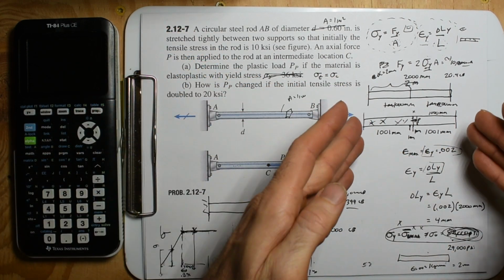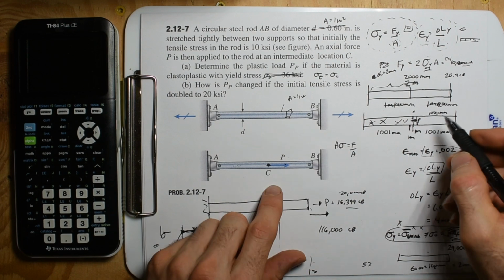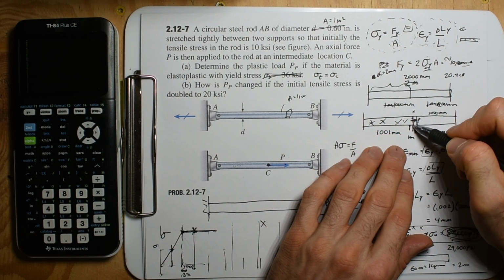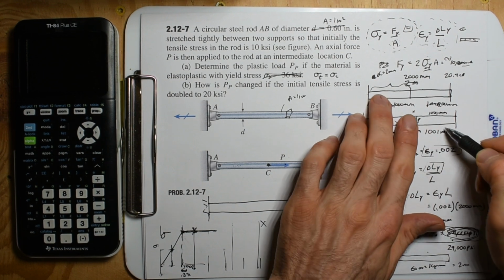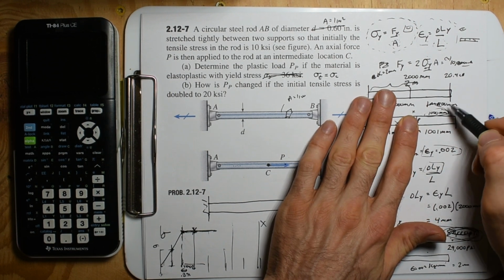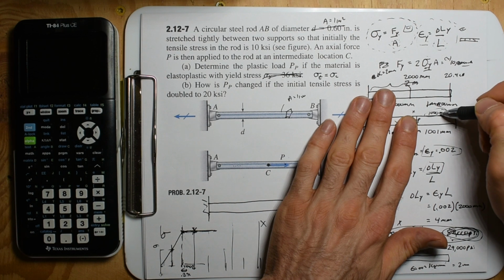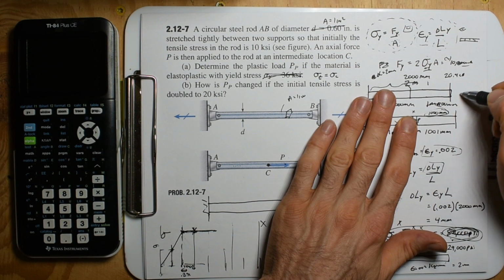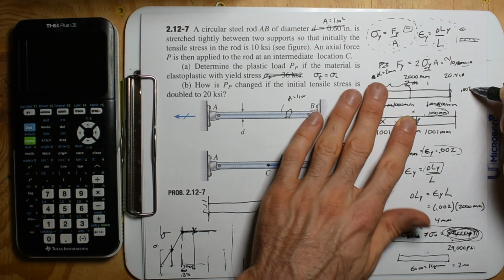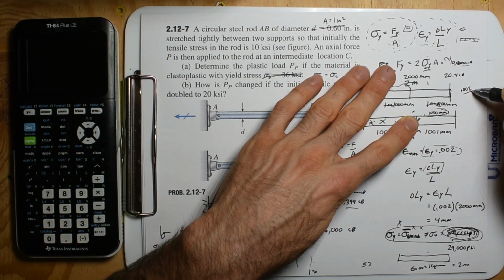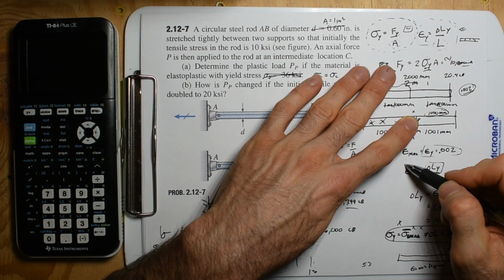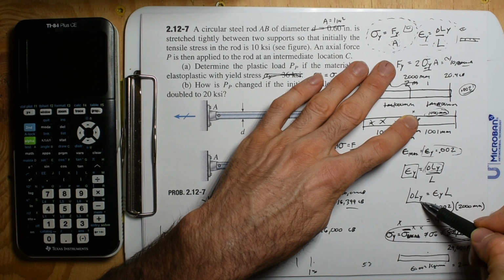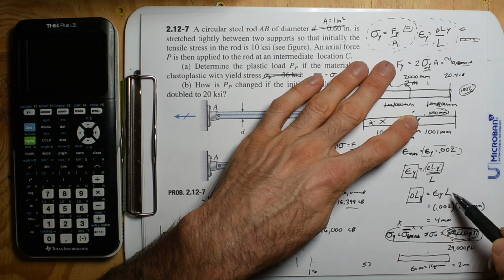So that problem was answered the first time I tried to solve this, but now I'm just showing you from a change in length perspective. So let's go back to it. We moved this 1 millimeter. This one went plastic, and this one's just happy as a clam. Now, how many millimeters can we move this one? Well, it initially was a 1 meter bar, we can make it 0.002 strain. And if you lose your mind and you don't know what the strain means, go back to the equation, rearrange it and solve for what you want. I want to solve for the change in length. It's just strain times length.